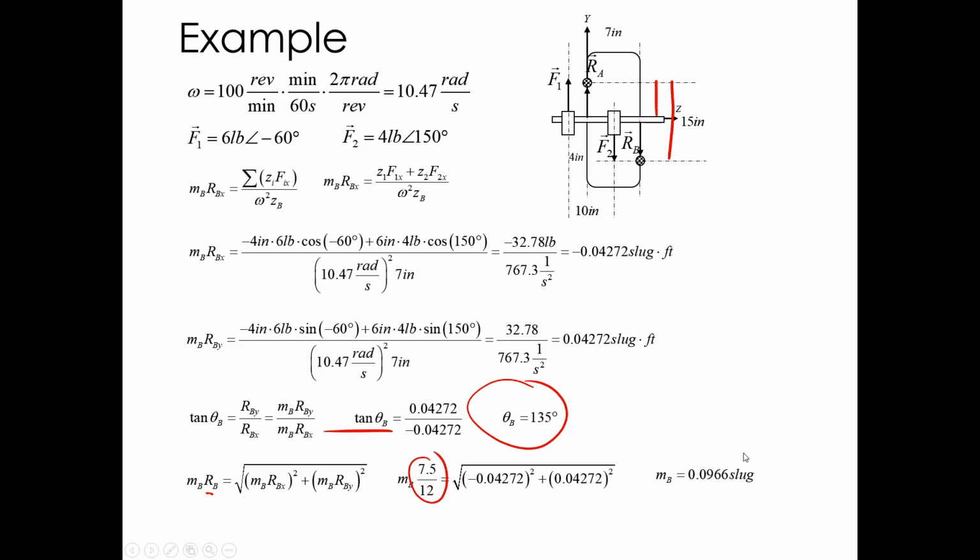So solve that out, I get 0.90966 slugs. So that is a tenth of a slug, which is 3.2 pounds. So I have to put a 3.2 pound weight on this thing. This is terribly, terribly unbalanced at 100 RPM. This is not a very realistic example. The numbers are way off from a real balancing weight. It'd have to be a pretty terribly balanced rim to need a 3.2 pound weight stuck on it.